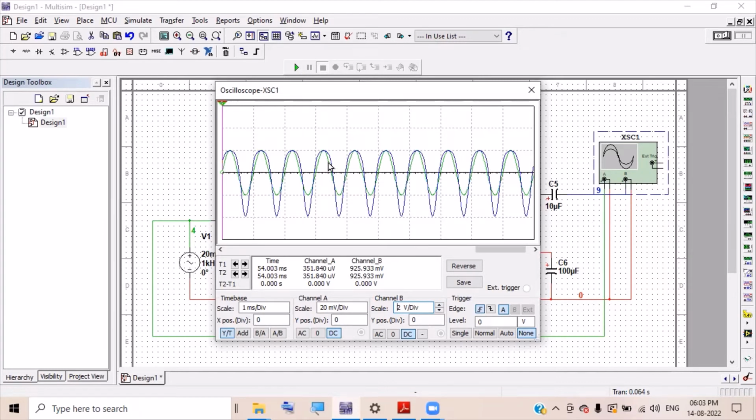Gain is very high, because of that the waveform is not exactly a sinusoidal signal, but very much close to that, and this is acceptable. And here we can see that the gain we are getting is much higher than the single stage gain. I hope all of you remember that the single stage gain in dB was 36. Now let us go ahead and see what is the gain we will get.